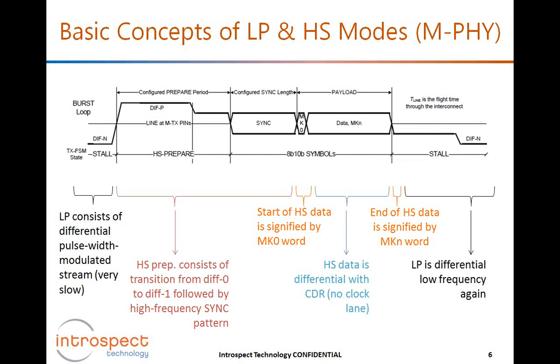The next slide is M-PHY. And again, very similar concepts. Like I said, the high level is the same, except that the base technology is different. And what M-PHY has decided to do is slightly different. M-PHY decided that the black section, the low power section, will still be differential mode, so it'll still have a plus-minus differential pair transmitting data.